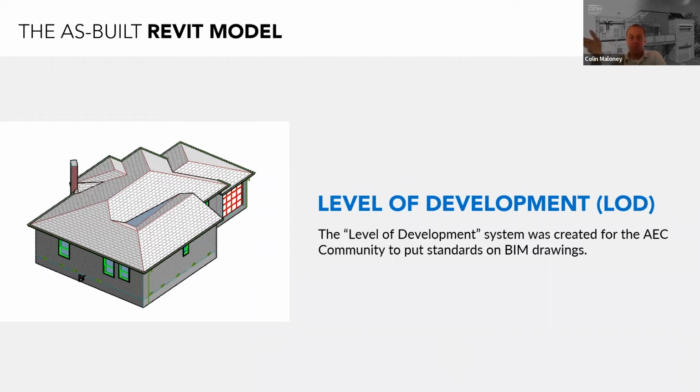When modeling as-built plans, LOD 200 to 300 seems to be the applicable range, since you're assessing a structure that has been built from the outside. All interstitial spaces are inaccessible, and their construction cannot be assumed, at least not by me. Maybe some of you out there want to make those assumptions.